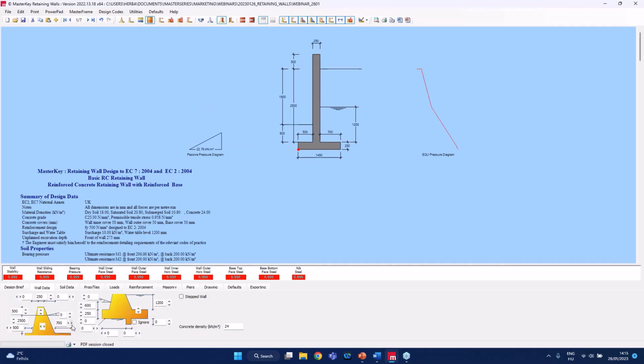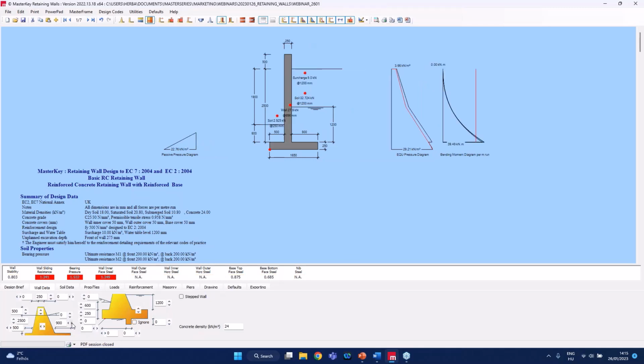And as you can see, I'm clicking on the button and changing the parameter, then the dynamic graphic is automatically updated, and the program recalculates the design, the calculation. And as we move up, we get a situation where suddenly there is no overturning here and no sliding.